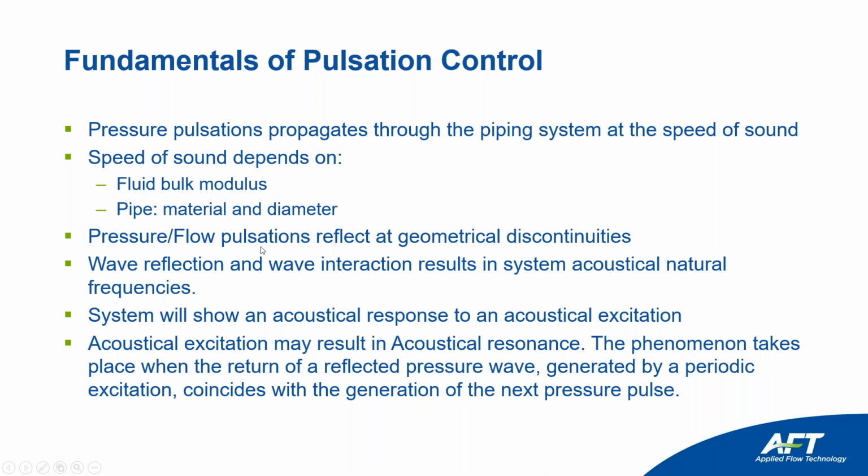Pressure and flow pulsations reflect at a geometrical discontinuity. So anytime you have valves or a change of diameters, there will be a reflection of the wave in that section. Wave reflections and wave interaction result in system acoustical natural frequencies. That is why it's important to model properly the location of any discontinuity in the pipe when you're going to do an acoustical analysis.